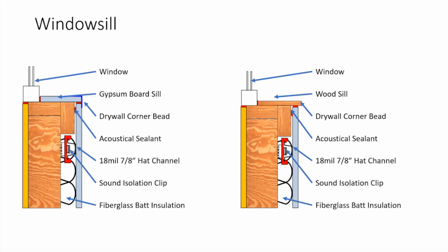And again, when you're looking through these details for your particular project, think about that cavity path and that structural path. Do we have a continuous mass layer? And is that continuous mass layer acoustically separated from the other side of the wall, partition, whatever it is? If you really think about those two things, thermal bridging and air barriers, that can help you look through these details and find potential weak points in them.